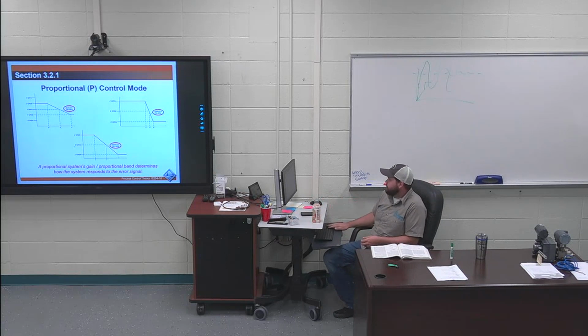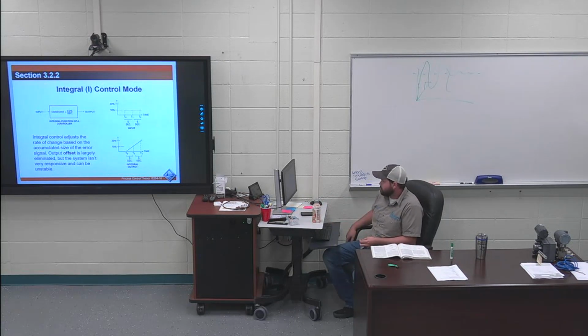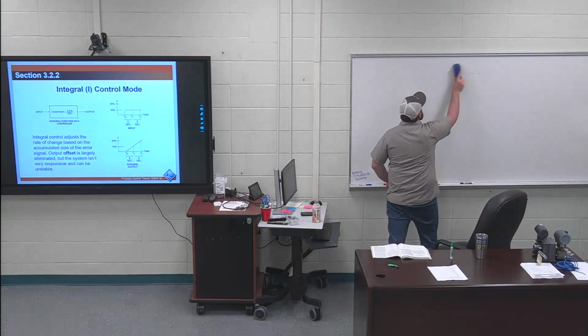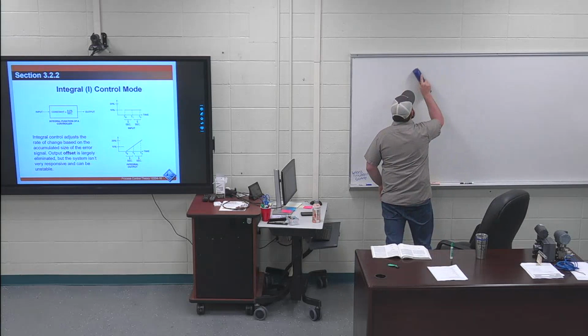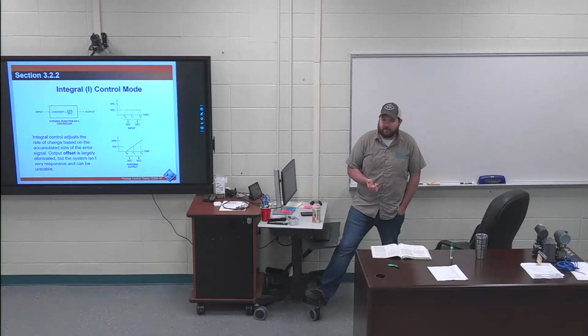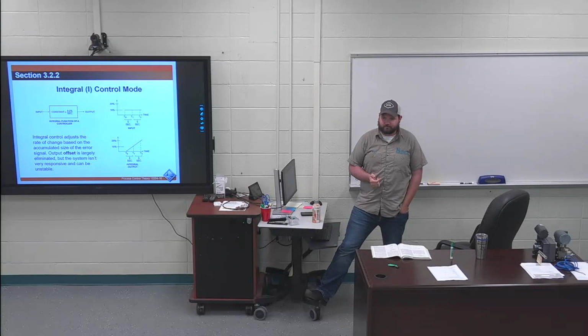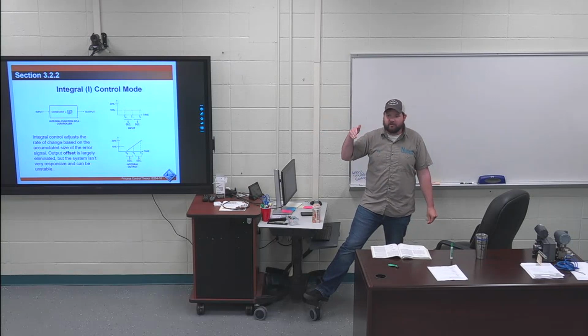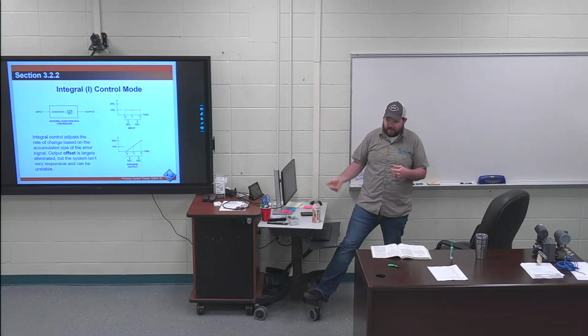Page 34 and 35. So what I'm gonna say about integral. And these are proportional, integral, and derivative. One way I want y'all to think about them is like the scope of a gun, where you have the coarse adjustment and then the fine adjustment. That's kind of how this is working. Your coarse, big adjustment is your proportional, and then integral is your fine tuned adjustment, and then derivative would be even more so into that. So the tighter and tighter tolerance of control you want, the more you add.